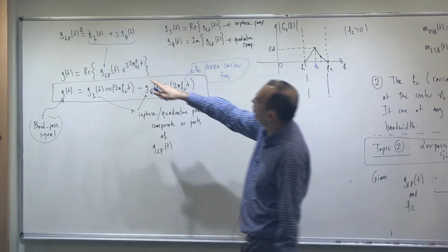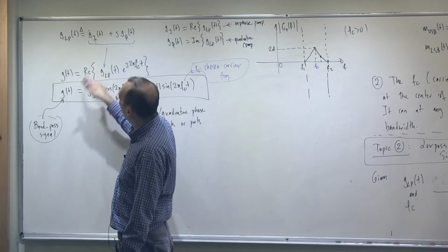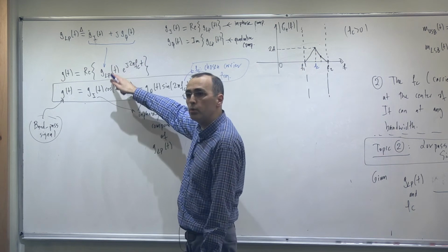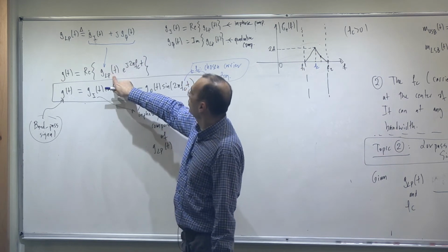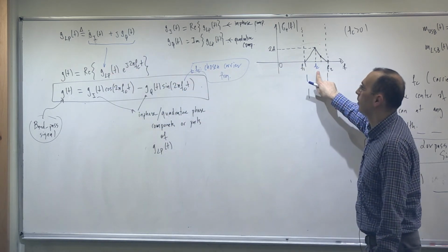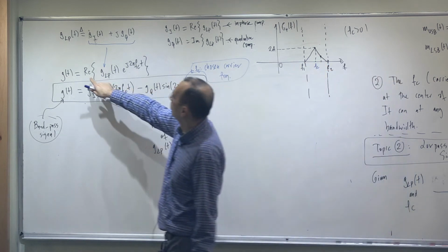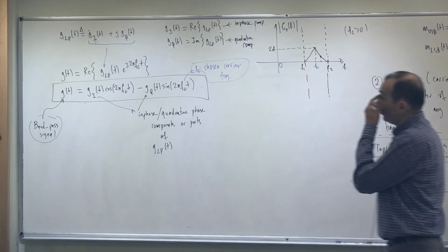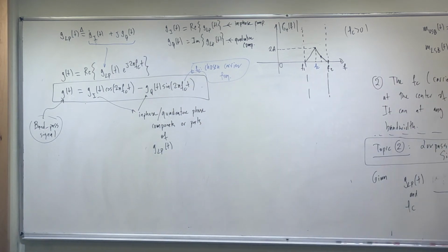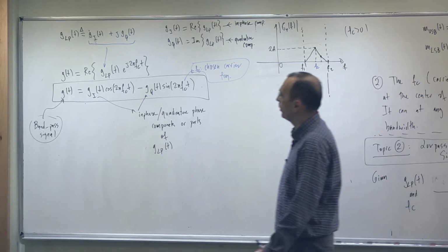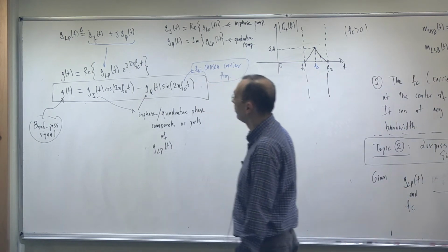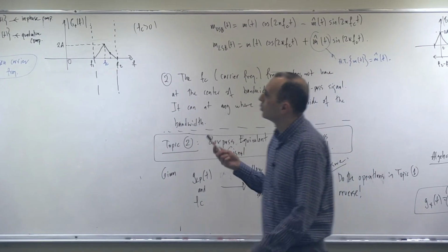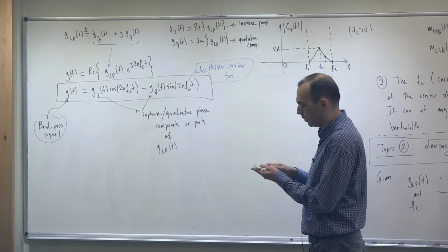Now from the low-pass equivalent, it's topic number 2. How can you get back the original bandpass signal? So from the low-pass equivalent, do the reverse operations. Given the low-pass equivalent, modulate it to the carrier frequency, and then take the real part of the signal in time domain. Okay? You get this done. So this is the basis of all kinds of communications, digital communications, radio communications, analog communications, etc. Because this is essentially the bandpass signal representation. Okay. So all bandpass signals are represented like this.